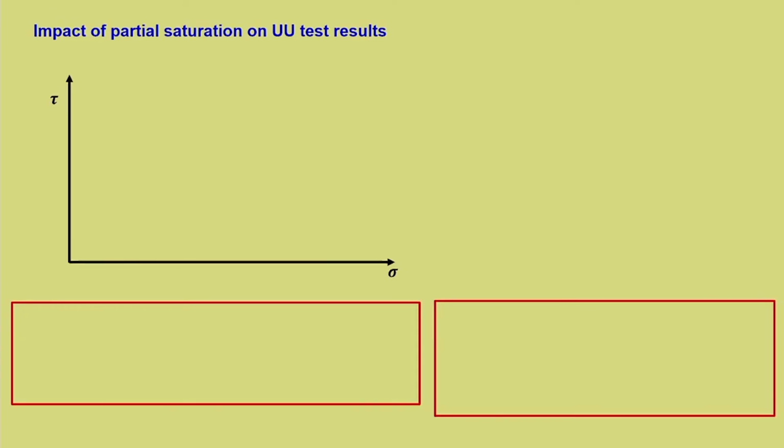So that is the impact of saturation. Let us see what is happening. Now this is sigma 3 1, where some of the voids get closed because of the expulsion of air. Sigma 3 2, again some volume closes, and you can see that the deviatoric stress keeps on increasing. Deviatoric stress keeps on increasing means the diameter of the Mohr circle keeps on increasing. Up to sigma 3 4 there is an increase in the Mohr circle. Beyond that the Mohr circle diameter more or less remains constant.